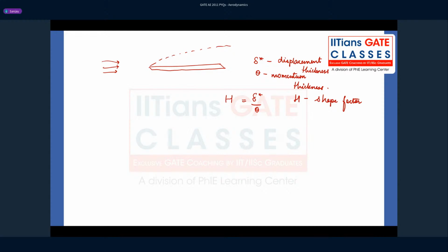So they are essentially asking you to find out the shape factor in this problem, right? Let's see how to solve this. Now, they have not given you any velocity profiles. You know the definition of displacement thickness and momentum thickness in terms of the velocity profiles. We can integrate and find out, but they have not given you any velocity profile. However, since this is a well-established flat plate boundary layer problem, we always have the Blasius solution.